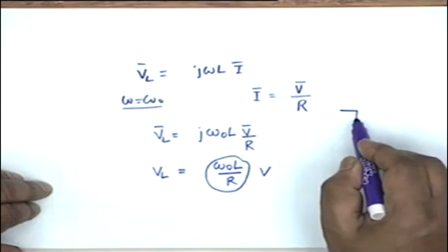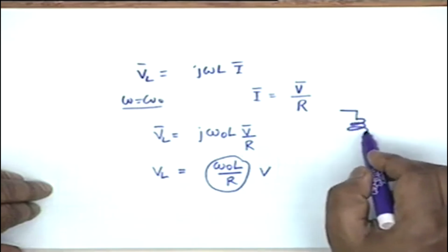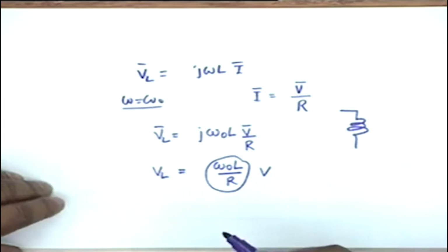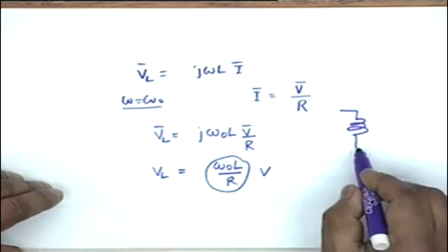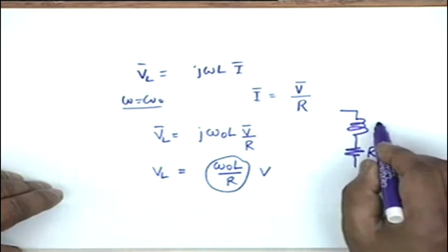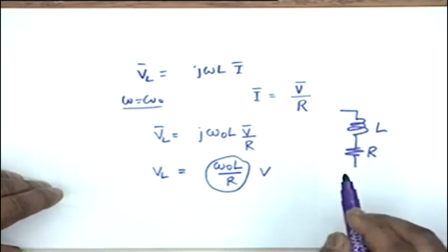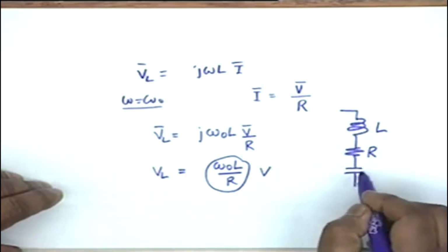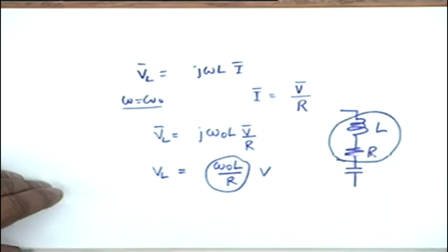The resistance that we are talking of basically belongs to the inductance. You cannot make an inductance without a wire, and a physical wire shall always have a resistance, and therefore this resistance that we show usually is the resistance of the coil, or this resistance determines the merit of the coil.